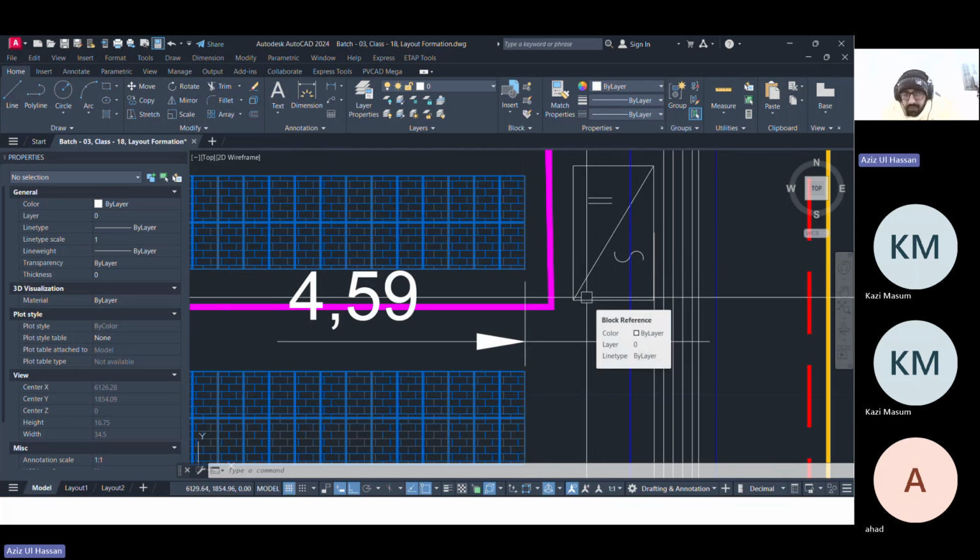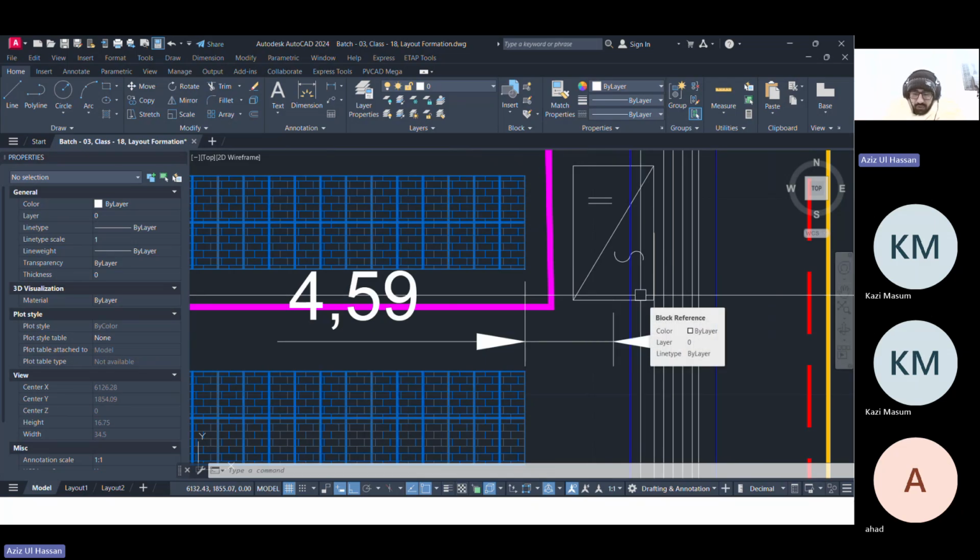But when we are actually placing the inverter, we have to check the actual length and actual width of the inverters, like the top view. Here are its depth and its length. So you have to mark the inverter as per the actual size, and then you have to mark the actual length as per your site recommendation, as site condition.